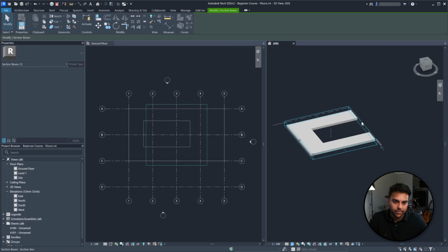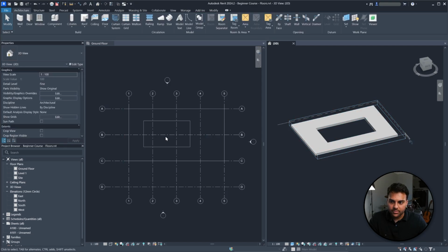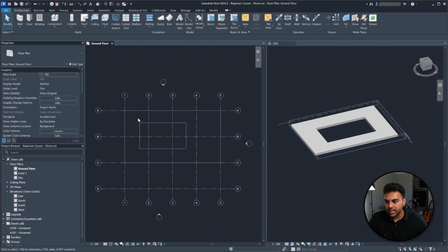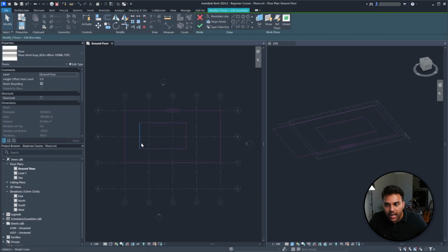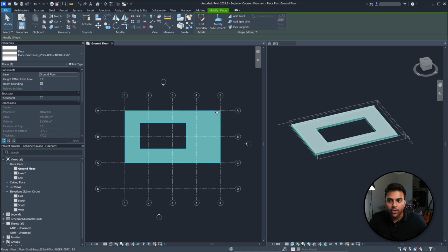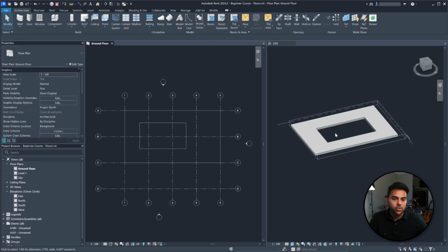And the reason you can't see it fully, it might look different, is because my view is not extended. So you want to drag that view, and you'll see that this floor I created, and I clicked edit boundary, and within there I put another floor or like another box in there. Once I click OK, since I was in the same editing mode, it actually modified the floor which was existing and it cut a hole in the floor, right? So you can do this with anything.